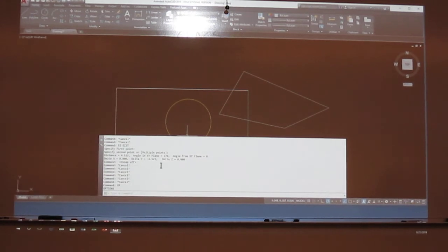Okay, so you get this command. Now this pops open your text window. You can go up through here to the very first command you had when you started the program. Just arrow key up. So you can kind of come out and say, oh, well, here's the distance command. Now everything in here is copyable. So if I needed to send this information to somebody, I could just come in here, highlight it, Control-C it, drop it into a Word document or whatever, and send it to somebody. So if it disappears, you go to the text window, and that will show you everything that you have.